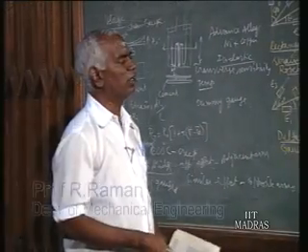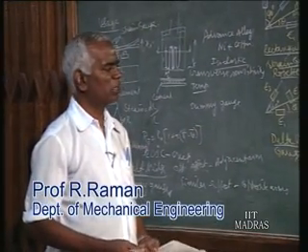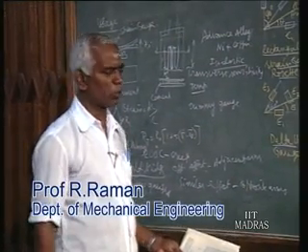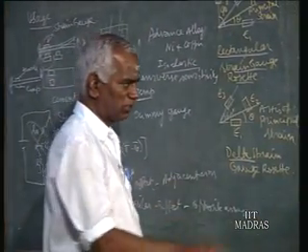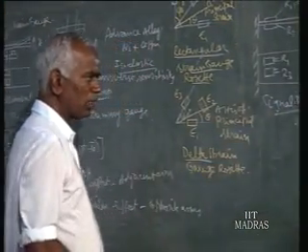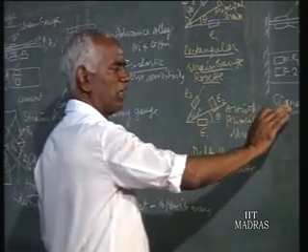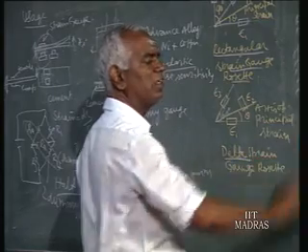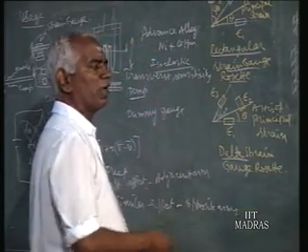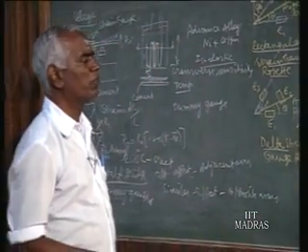Noise is coming, we have learnt under amplifier, Johnson's noise, in terms of some microvolts, and our signal should be much more than that noise. This is what is meant by signal to noise ratio. Otherwise, if signal is also of the order of a few microvolts, that will be lost in the noise, so you don't get to know which is signal, which is noise.